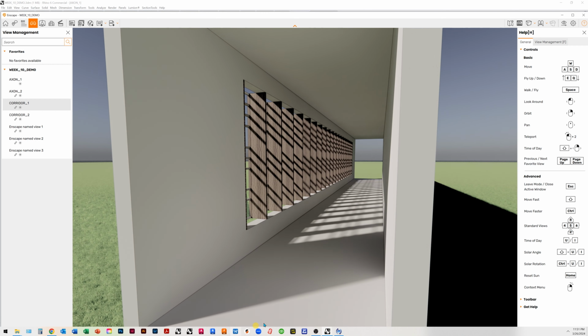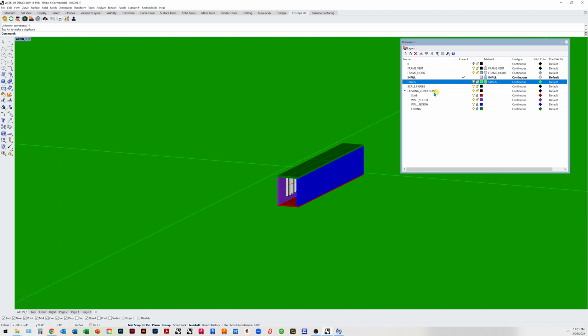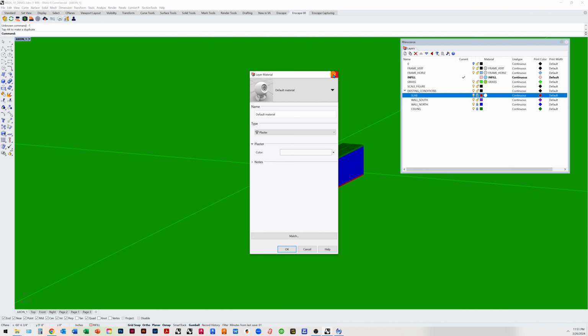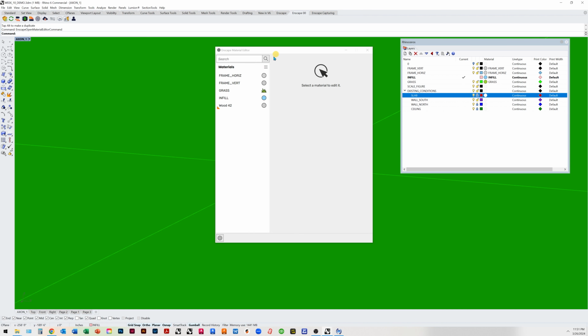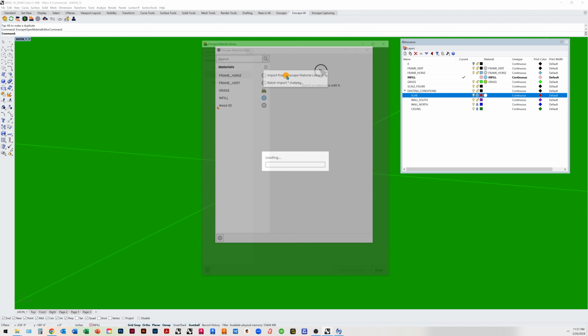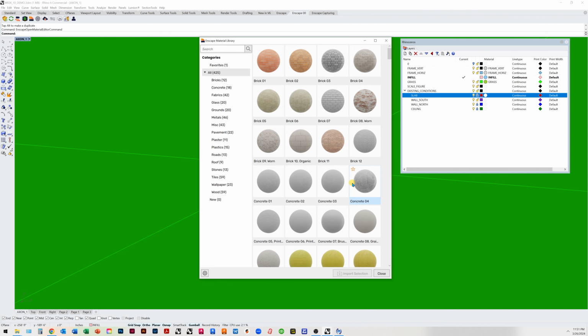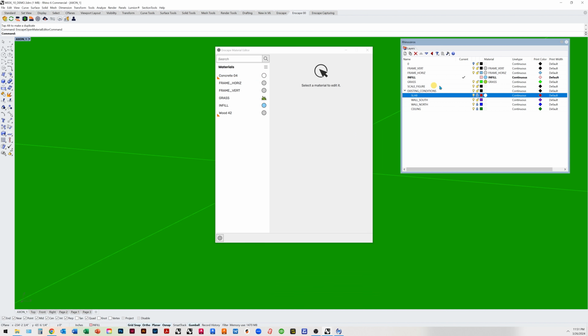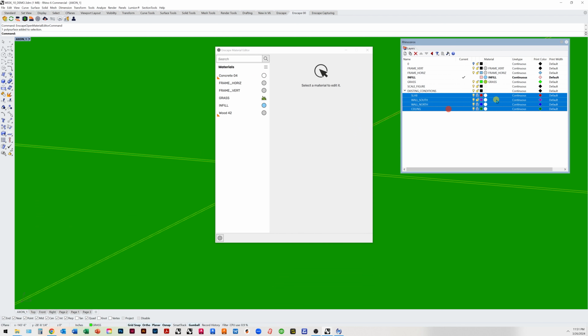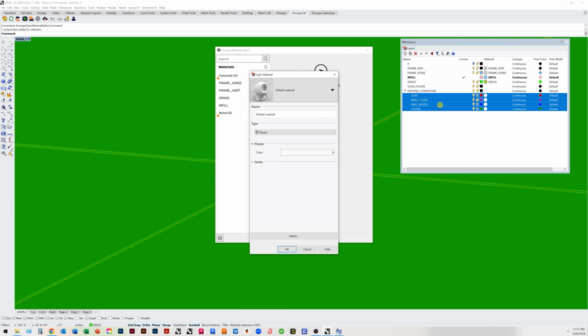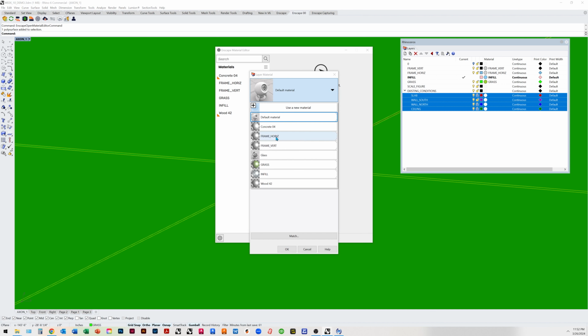You don't need to do anything in the corridor, but again, if you wanted to explore some of those materials, say you looked at the slab, here's one thing you can do is instead of doing the 2 steps here, you could come into your materials and you could find a couple of materials you want to use on the project. So say we want to make that slab underneath concrete. Maybe the whole box wants to be concrete. Let's import concrete. Now we've got concrete here, and say all 4 of these want to be concrete. We can click on that, and now we can choose concrete.